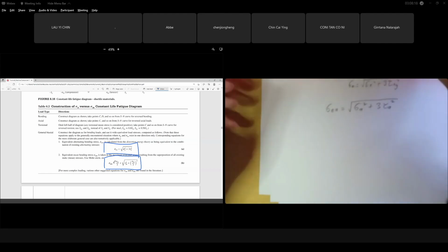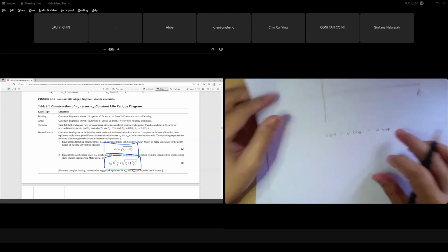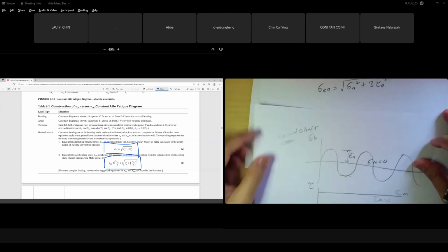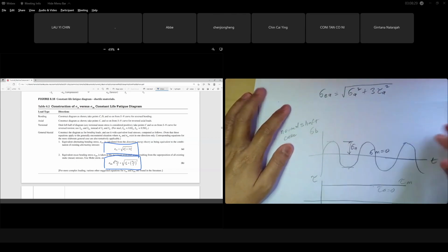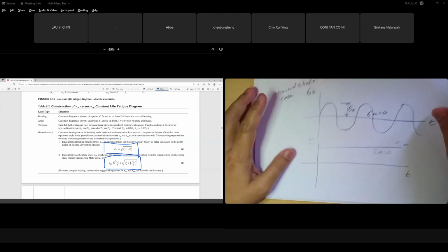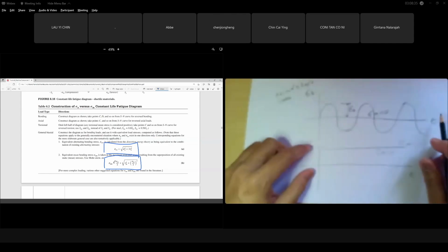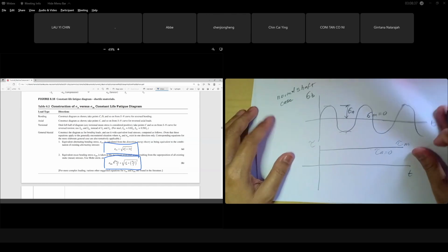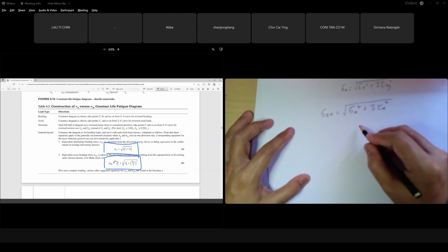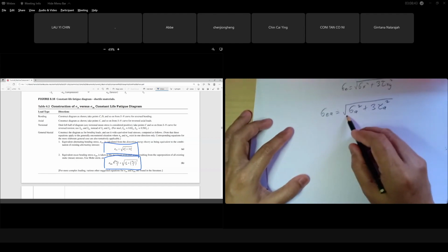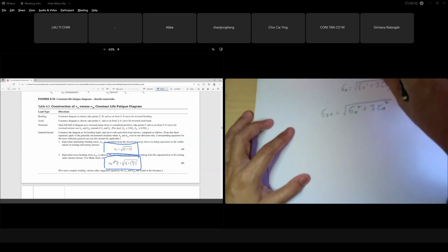For the shaft case, we want to calculate sigma A for the shaft. Do we have an alternate for the shaft in pure bending? We said we have sigma and tau torsional stress, right? Do we have sigma alternate, class, for the shaft case? Because we want to find the equivalent. Do we have sigma amplitude? Do we have amplitude for the shaft?